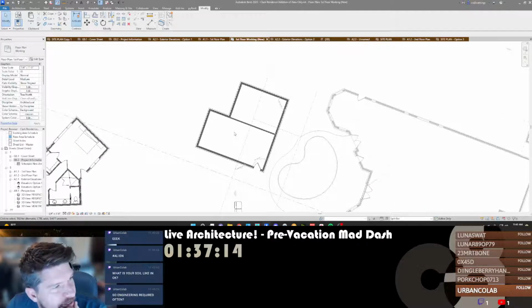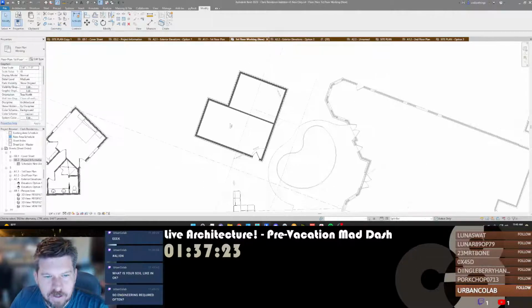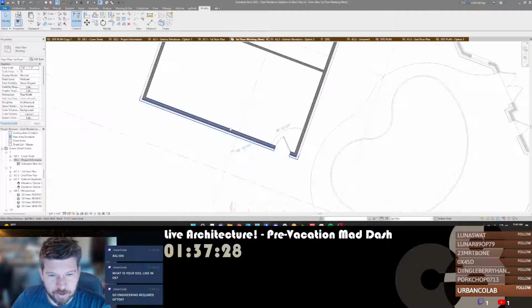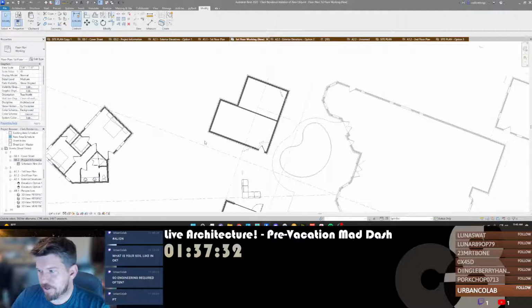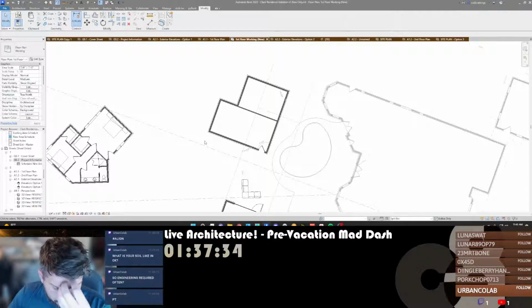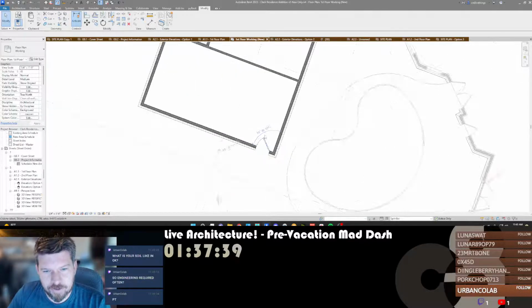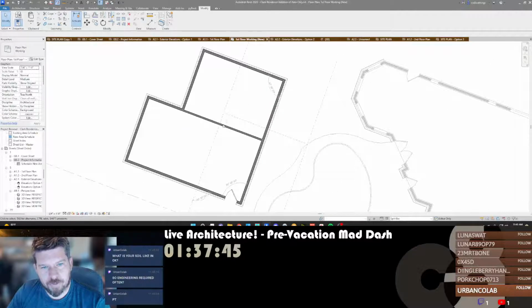So engineering is required in the sense that most of the companies that pour foundations here have in-house engineers. There's a lot of post-tension slabs that go in, which I'm not entirely sure is the best way to do it. I don't know why we don't do more grade beams. Typically on residential projects, I don't end up hiring a structural engineer because the foundation people the contractors use usually have in-house engineers providing those drawings for permitting and whatnot.